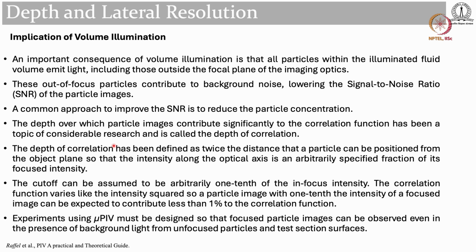So basically, experiments for micro PIV must be designed so that the focused particle images can be observed even in the presence of background light from unfocused particles and test section surfaces. I hope you understand the meaning of this, because as we have seen, there are particles present in the background of the focused plane, and there can be reflections and other things from the test sections also, but your experimental setup should be robust enough that the focused particle images can be observed even in the presence of these unwanted sources of light.